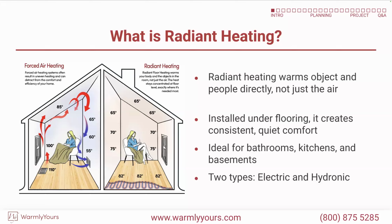What's great about this drawing is, on the left side, imagine if this were a basement. Most of the time in a basement, you'll have the air vents in the ceiling above you instead of down in the concrete slab. Sometimes you do, but most of the time it's up here. So if you have a vent up here at the top, that air comes down a little bit and then goes right back up to the top where it gets hot, and then as it cools down, it comes down and goes into the cold air return.